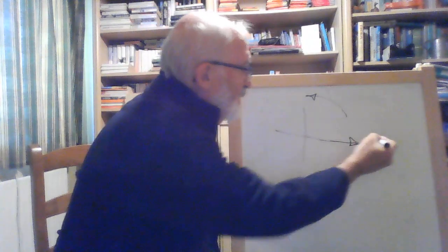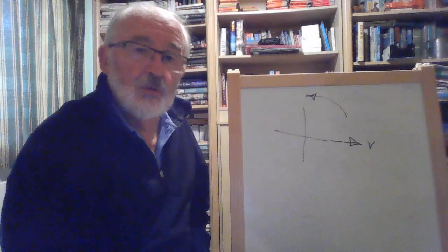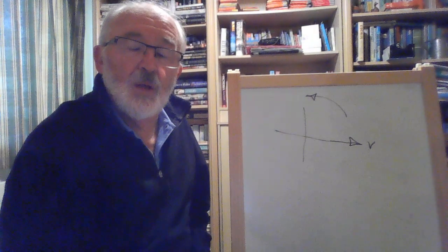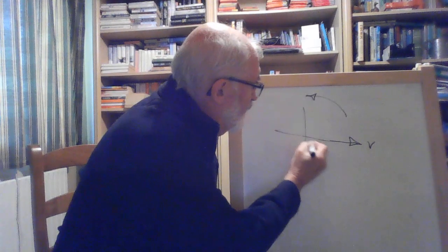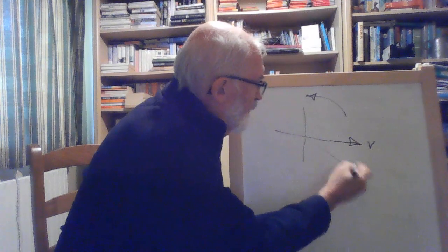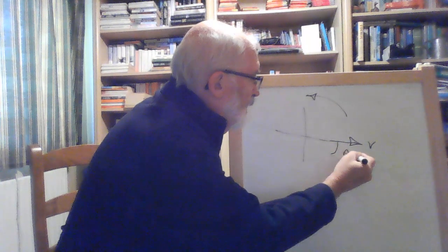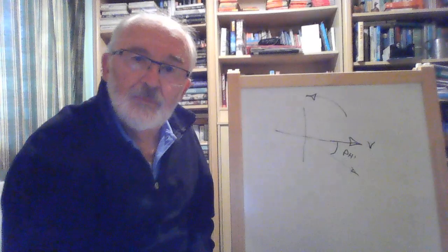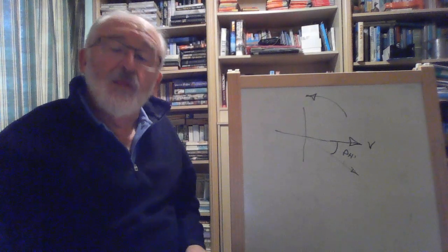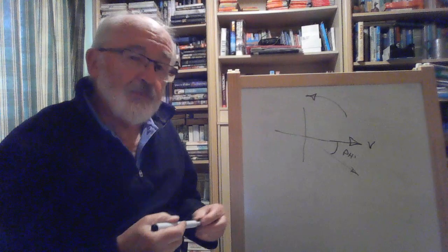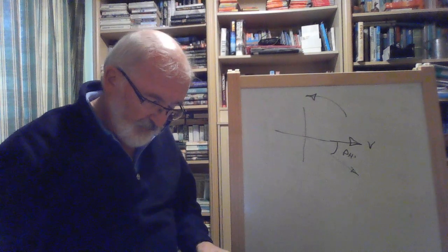There's the voltage, and for an inductive circuit or the general pattern of inductive loads, we find that the current will lag by this angle phi. Okay, so that's enough of it. And that leads us into the concept of power factors, which we will look at a little bit later in the chat.